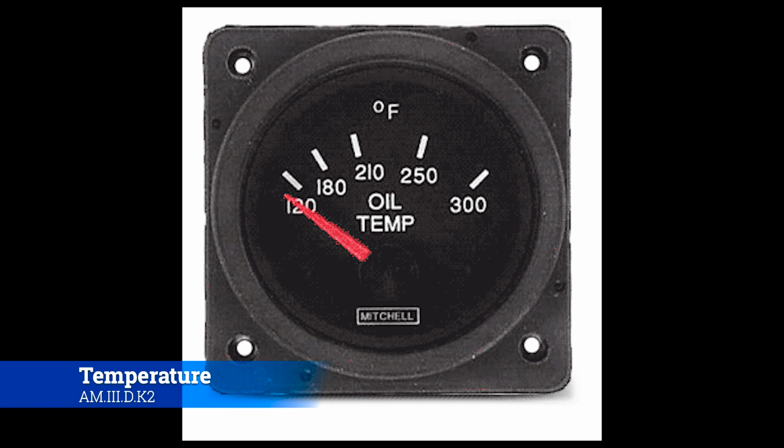So therefore, you'll start to see the engine run hotter and hotter because the oil is being less and less effective, leading the oil temperature to actually go up. And so there is definitely cause to say, hey, look, you've got super high oil temps. First thing to do is check the oil. If the oil is good, then we're going to change the oil, and then if it runs hot again, then we might have another problem of some other variety. But those are kind of your base troubleshooting steps.